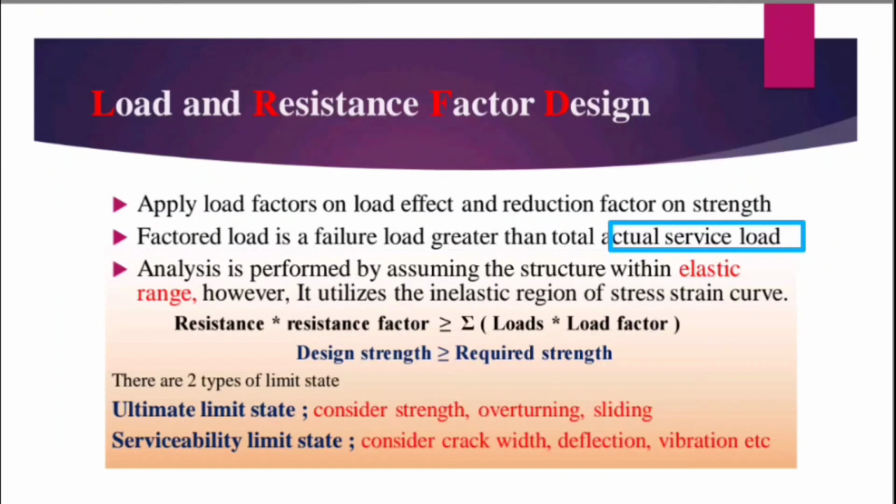So today remember this, the working load is less than the service load. Service load is the maximum load that might be experienced. So remember this. On the service load we will apply the load factor. We multiply the service load by the load factor, and we get the factored load. So the factored load is a failure load after which the structure might fail.